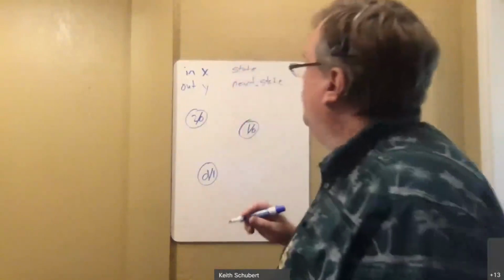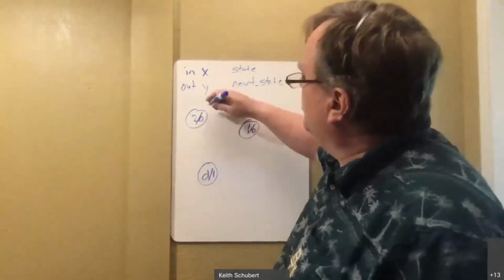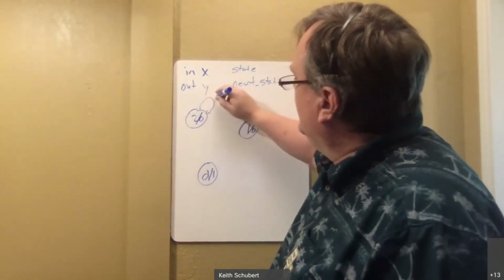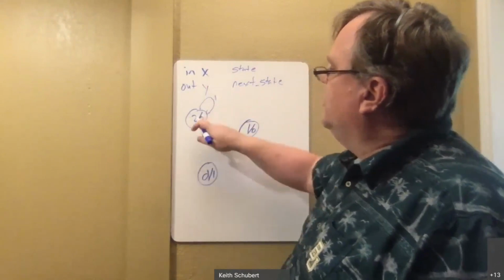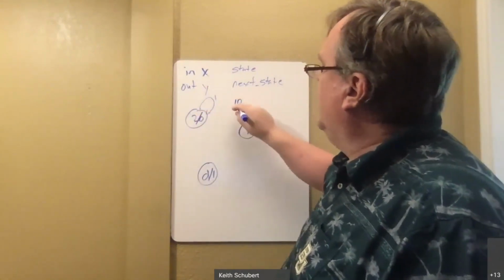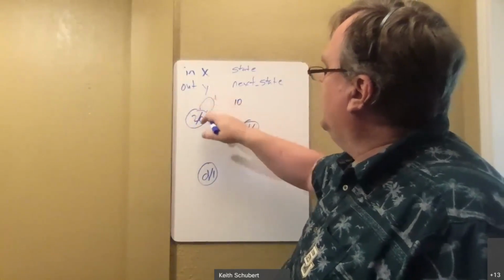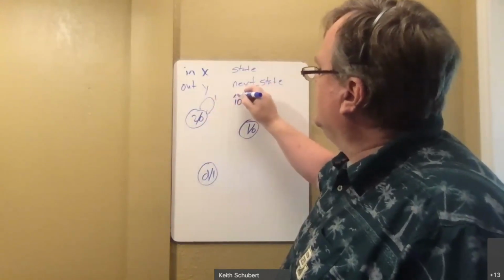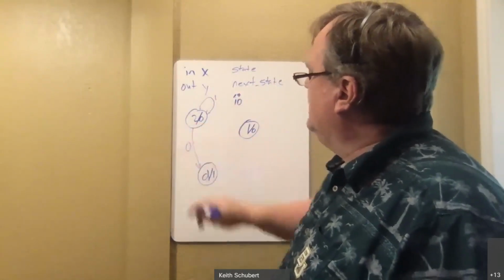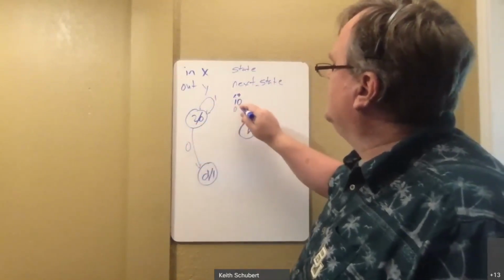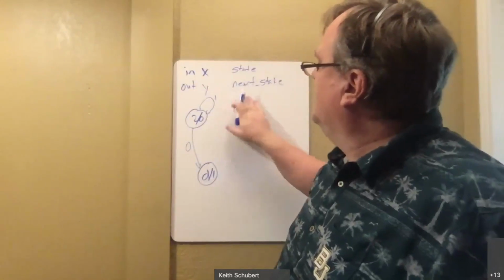So if x is equal to 1, then I am going to go to 1, 0, which is 2. So I'll get an arrow that looks like this if x is equal to 1. We usually just put the label of the inputs along the arrow itself. So it'll start at 2 and it will go to 1, 0, because it's x 0, and 1, 0 is 2 in binary. So it starts at 2, and when x is equal to 1, it goes to 2. If x is 0, then it's going to go to 0, 0, which is part of my default state. So when x is equal to 0, I'll get 0, 0, because it's x 0 as the state. That completely handles the situation of 2.